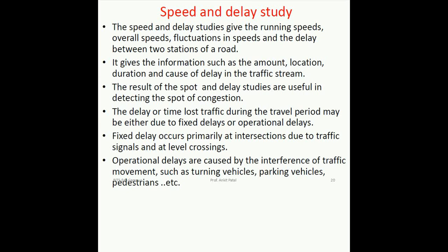Speed and delay study. The speed and delay study gives the running speeds, overall speeds, fluctuations in speeds, and the delay between two stations of a road. It gives information such as the amount, location, duration, and cause of delay in the traffic stream. The results of the speed and delay studies are useful in detecting the spots of congestion. The delay, or time lost by traffic during the travel period, may be due to either fixed delays or operational delays.